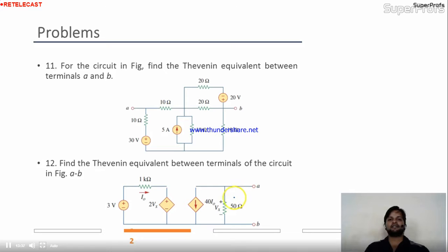To calculate the resultant resistance in a dependent sources circuit, the standard procedure is, across the points A and B where we have to calculate the RTH or equivalent resistance, we put a battery voltage source V, consider the current I because of that, and V by I is nothing but the RTH, or R equivalent, across A and B of the circuit. But another way we can solve this.